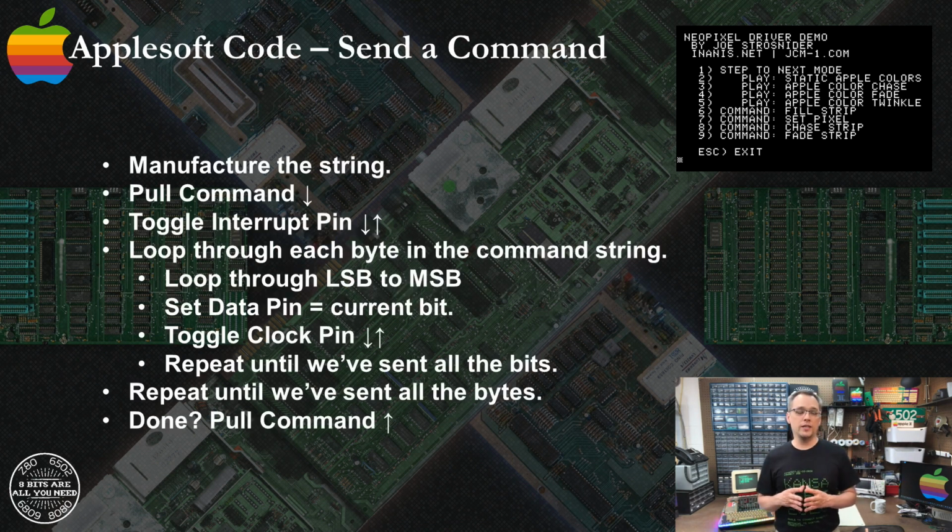Sending the command works like this. We set the command pin low, we toggle the interrupt pin, like that, so the Arduino knows we're sending a command. We then loop through each byte in the command string, sending bit by bit.